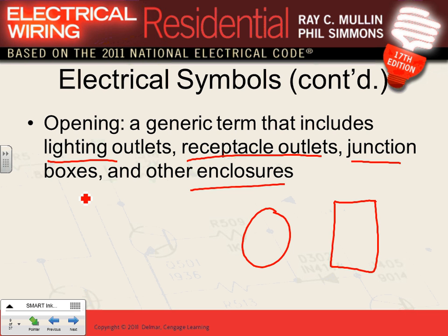Has anybody ever estimated based on openings? Yeah. So some people estimate based on openings. Consider every receptacle an opening, every switch an opening, every light an opening, and then multiply them by 30 or 40 dollars, and that will get you your bid for that particular job. Obviously, you can't bid a hospital like this. That would be residential, and might give you a good idea, but for a hospital or commercial building, it comes in really handy for small stuff.